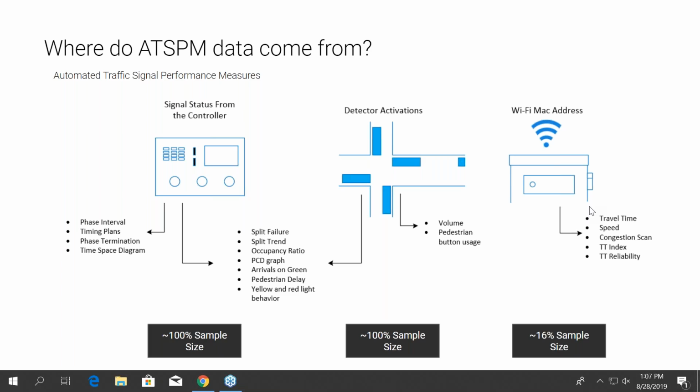Another piece of information that's available at actuated intersections, for example, is detection. So detection, the main purpose of the detection is for actuation purposes, but it's also possible to take that info, combine it with other sources of information that's coming from the controller, for example, and generate new performance measures. So for example, the stop bar detector occupancy during the green time and during the red can help us evaluate and understand the level of saturation of a movement, for example. We'll look into some of those examples later on.